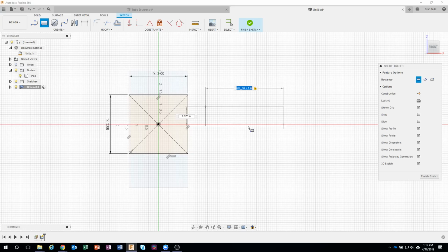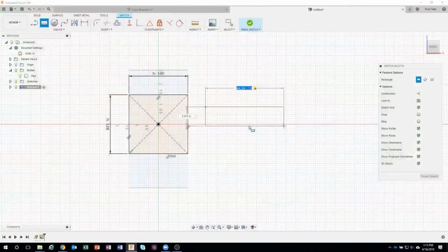So this is a great way, for example, if you needed to add some tolerance or some spacing for something. For example, you want the hole to be 1/4 inch plus a 32nd of an inch. You might have a variable called hole, and then you could even have a variable called tolerance. And then you would just say, I want it to be hole plus the tolerance. And then maybe you 3D print that or you machine it and it was just a little bit off. Well, then you can come back and tweak that tolerance variable and all of your holes will update accordingly. So neat little tip right there.